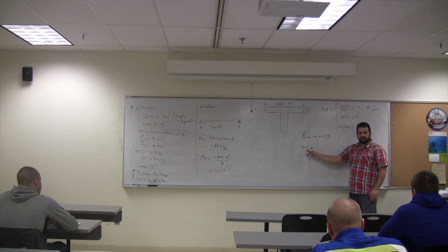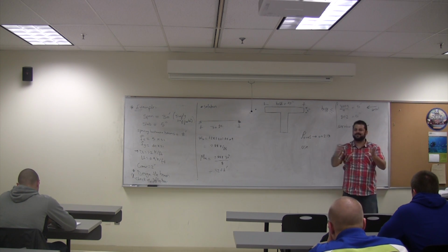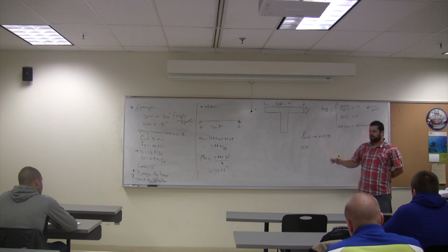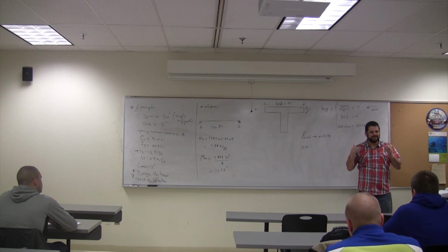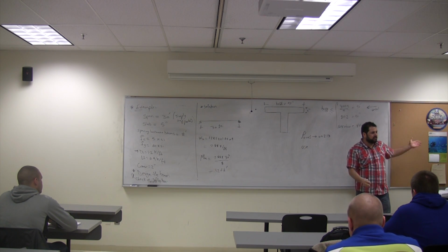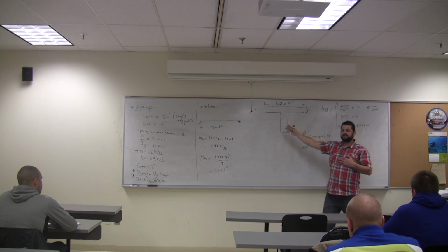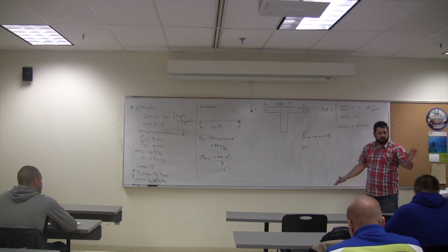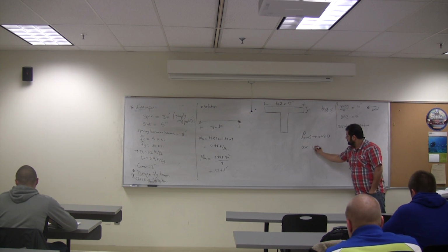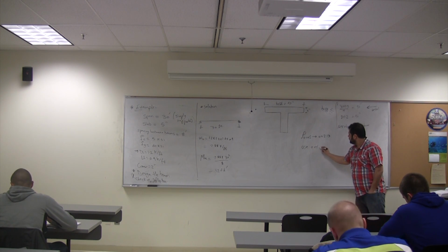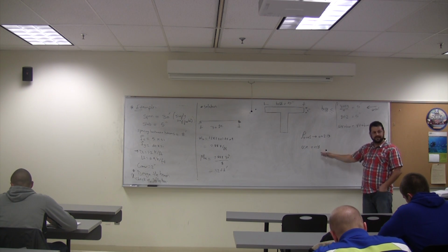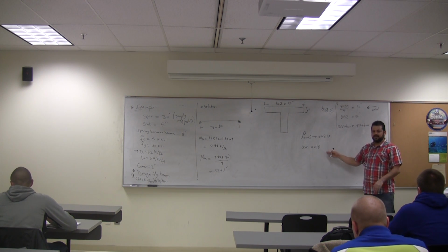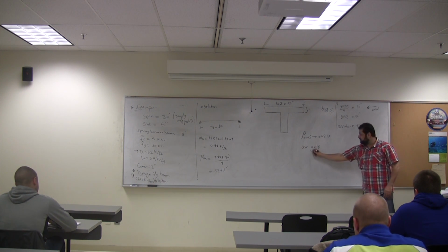Someone said, is this used that required? No, I'm a designer. That's why I'm telling you it's a sample solution. It's up to you. The prices of steel are high. They're going to say, why don't you use 0.5 of that? No, as long as I'm using something less than that, more than rho minimum, I'm fine. And rho minimum for T-beams is rho minimum for rectangle. Very small. So I'm going to use 0.018. Why 0.018? That's nicer to get R, right? From these tables. We don't want to end up with a calculation table. Okay? So that's what I'm going to use.